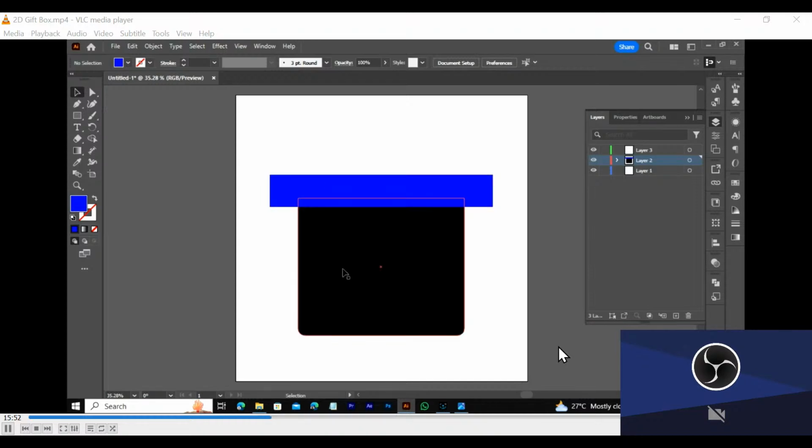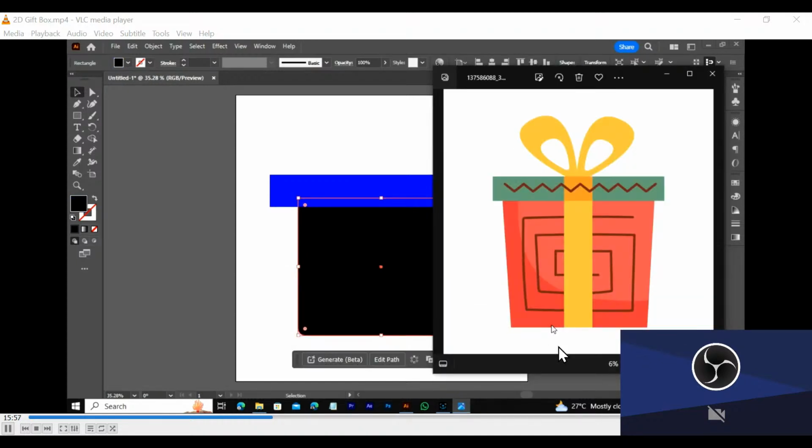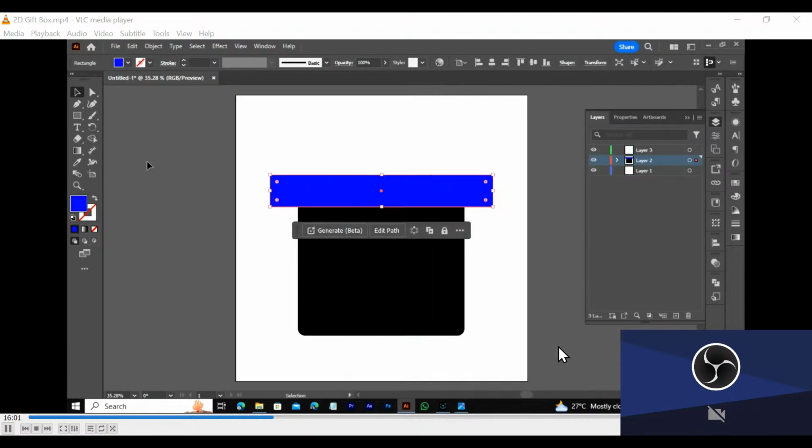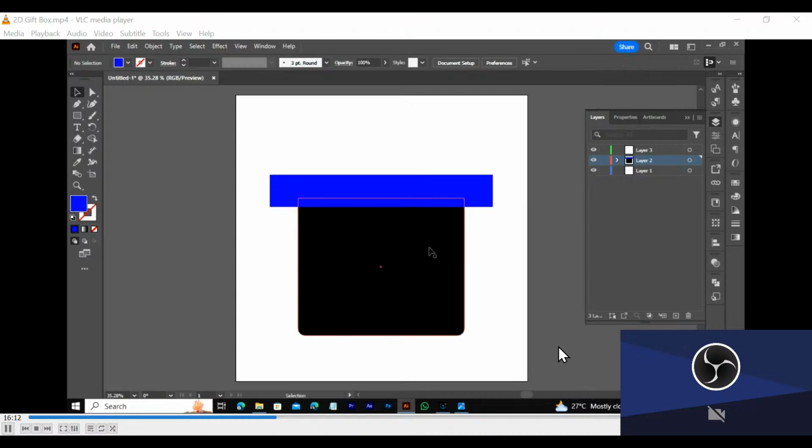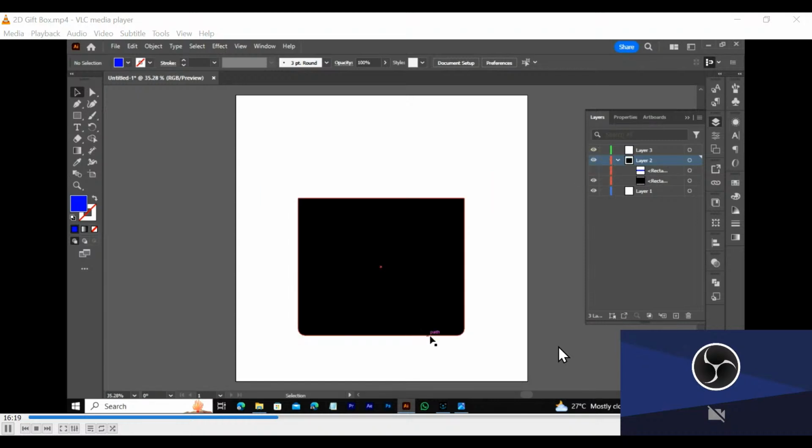So this is our cover, this is our bottom. Let's go back to our picture. For my cover, I want to give this a roundness. I want to give the 4 edges a roundness. This is 4 edges: 1, 2, 3, and 4. For our previous shape, I only gave the bottom roundness, and I left these 2 parts sharp as they are.